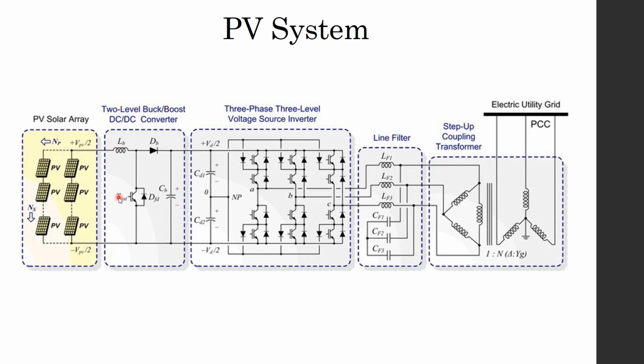It consists of a DC to DC converter. It takes the voltage here and converts it into another voltage. So the DC to DC converter, for example, if it is a buck converter, what does a buck mean? It means a step down DC chopper. So what does it do? For example, if we have here 100 volt, it will step it down to, for example, 20 volt, by changing something inside the converter called a duty cycle. By changing the duty cycle, we can change the output.